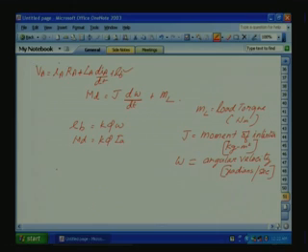So this will give our armature current IA(s) is equal to VA minus EB divided by RA plus LA into S. D by dt we represent as S. So this can be again rewritten, modified.